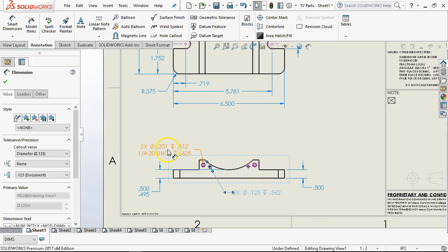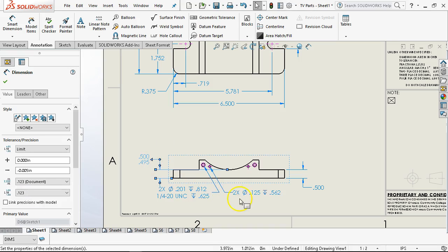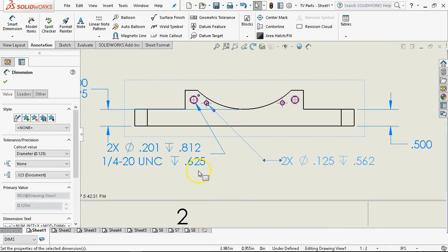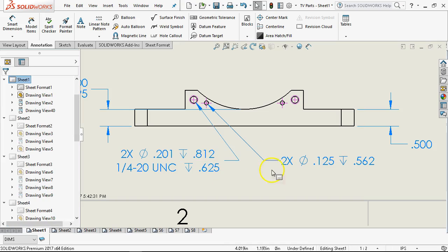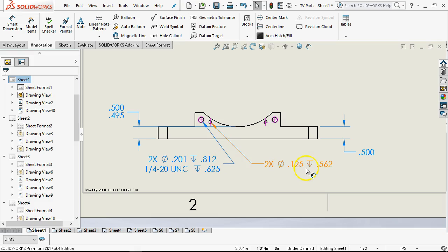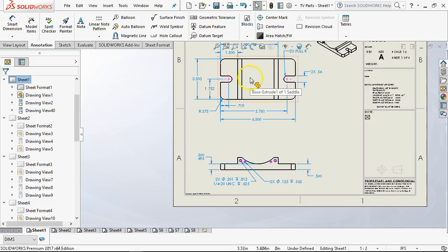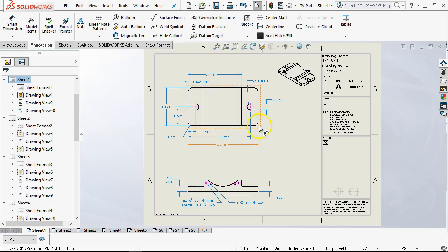All right, so I'm thinking that these need to be kind of down here. And the fun part with some of these dimensions, especially with the angles, is getting them positioned and keeping them in place. Because this is near side, far side, I have to make a choice. Right there, again, my preference is I'm not going to include hidden lines unless there is geometry that it can explain. To me, this is a much cleaner drawing.